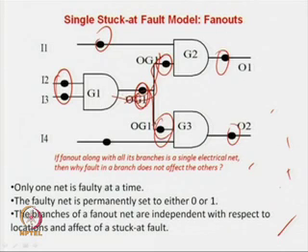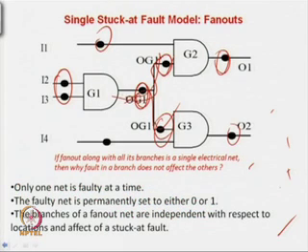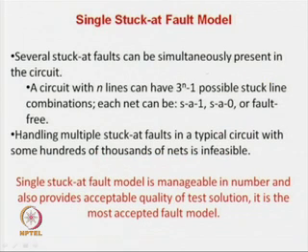It is not as good or as neat as a single stuck-at-0 and stuck-at-1 fault. Only we are verifying that there is no stuck fault, implying that the circuit is normal. So for that reason we also have to consider these things. Generally you can ask how many stuck faults at a time. Basically, each line can have a stuck fault, a pair of lines can have a stuck fault, 3 lines can have a stuck fault, and so on. But if you consider this, the number of stuck faults will be extremely high.